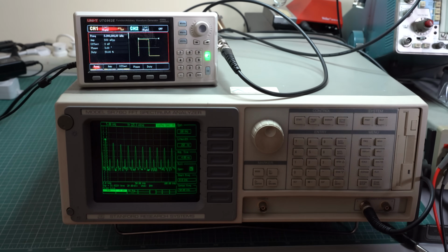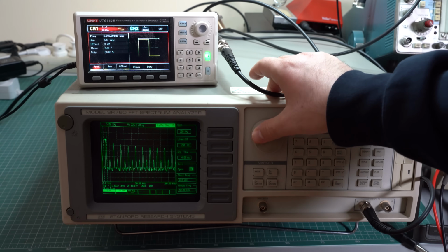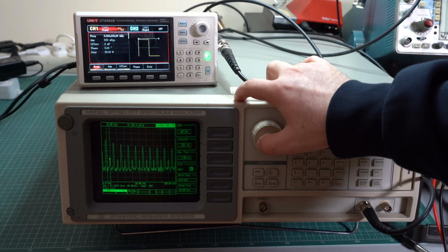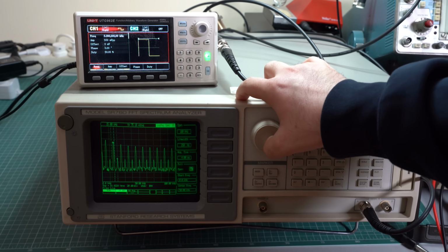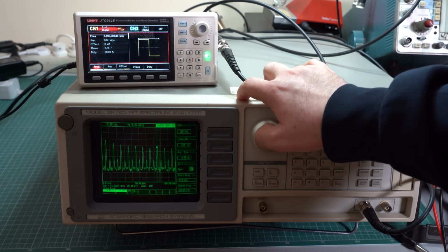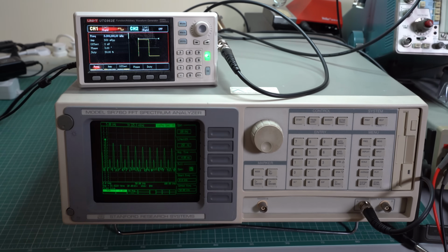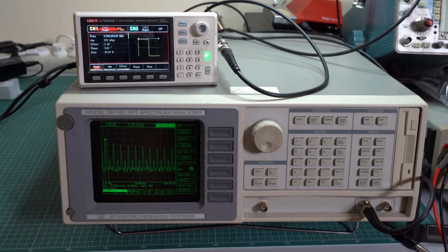So here we apply a square wave at 5 kHz, and you can see the fundamental right here, which is 5 kHz. But we also see the second harmonic, which happens at twice that frequency, which is 10 kHz. The third harmonic, which happens at 15 kHz, and so on. In theory, a square wave should have an infinite number of odd harmonics. But since our signal is not ideal and the spectrum analyzer can only have so much bandwidth, we can see a few of them. And we can only see so many harmonics due to the limited bandwidth of this spectrum analyzer. Not that the signal will go to infinity anyway.